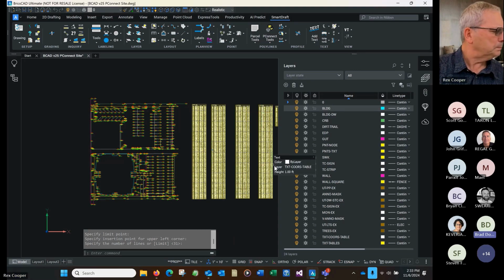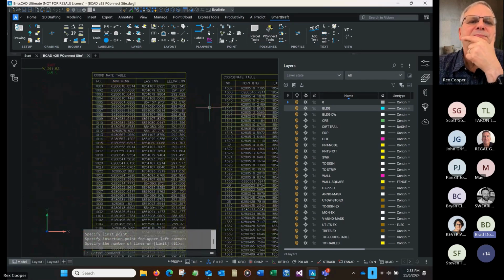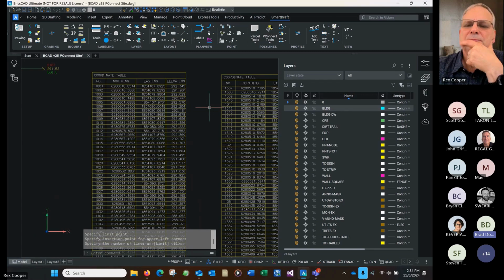Yeah, I did mention I'm civil engineering more based, not survey, but a similar feature that's in the SmartDraft with tables is line curve data, which will produce this similar type table. But for those that are doing horizontal control plans for your private work, or even data tables for roadways for things like curb alignments and so forth, it'll give point number, the length, the radius, the tangent, and then a description line. So somewhat similar to these tables, but more in a plan production type format.